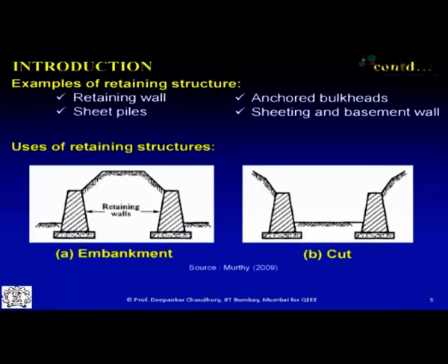It shows various types of retaining structures. Retaining structures can be a retaining wall like this, which I have also drawn on the paper and the slide I am showing, to maintain an embankment at a very different level than your conventional ground surface, which is at a much lower depth like here, or to maintain a vertical cut. So this is your natural profile of the soil, and we want to excavate and make available a cut portion, like any underground construction, metro, etc. So there also you need this kind of lateral supporting system or retaining structure.